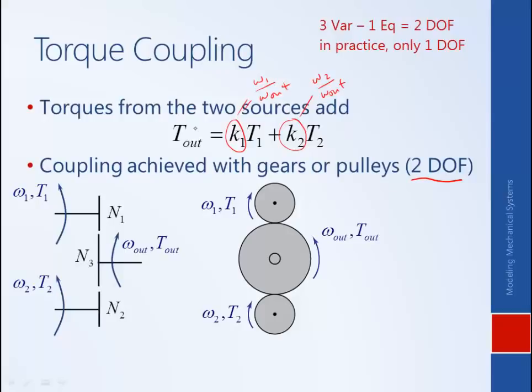And so T out is chosen by the driver. Therefore, we can choose the IC engine torque to be whatever we want, but then in order to get the output requested by the driver, that completely determines what the torque generated by the electric motor must be. So we can define one of the two, but then the other one will be constrained by what the driver's requesting.